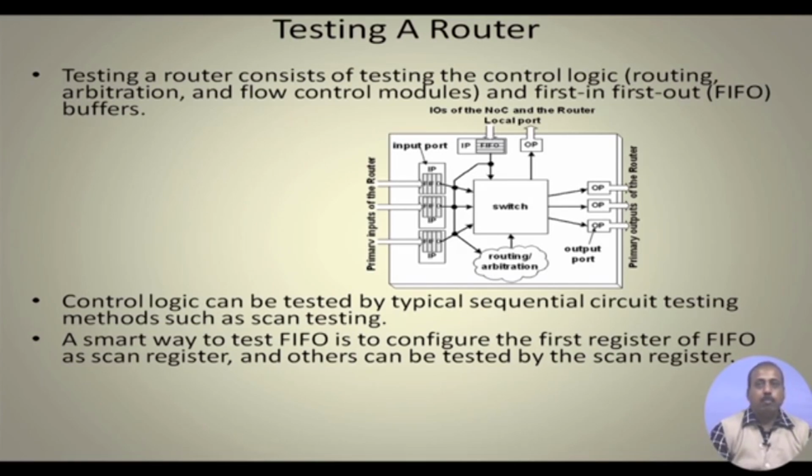But that will increase the complexity of individual routers, and as we have said, the individual routers are going to be very simple. So, this buffer depth cannot be large. Normally it is kept at 4 to 6, not more than that, and as a result a packet gets distributed over flits, and some of the flits of a packet will be available at a buffer of a router.